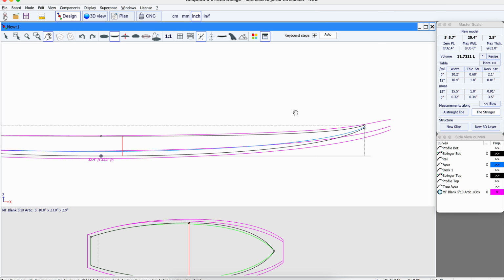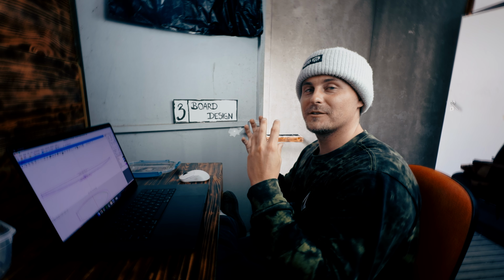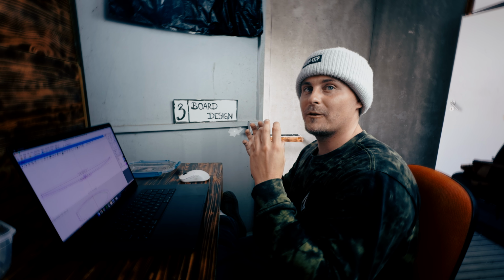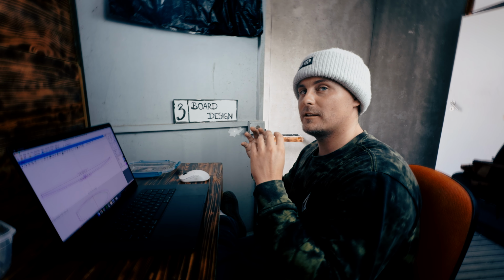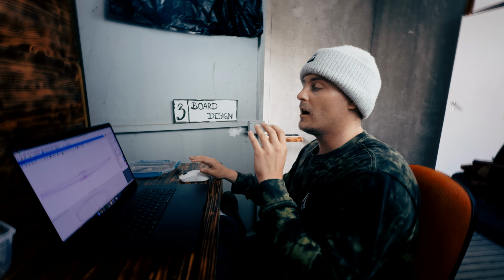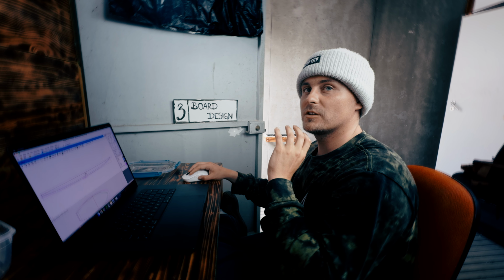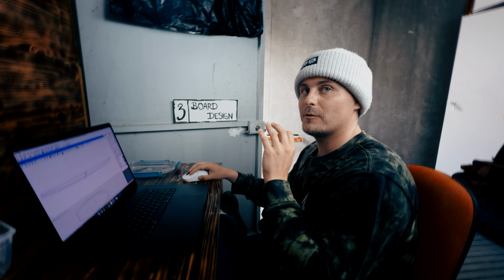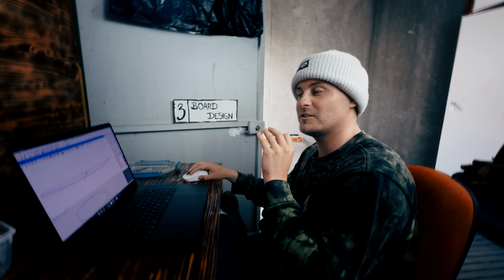And this is also when we speak about choosing the close tolerance blank. Let's say that the thinner and more narrow the blank you choose, and the more your design is on the edge and fits all nicely, the bigger the chance that it's gonna work. Also, it means that there is less material to take out, which means less work, which leads to fewer errors and less changing of the blank itself.